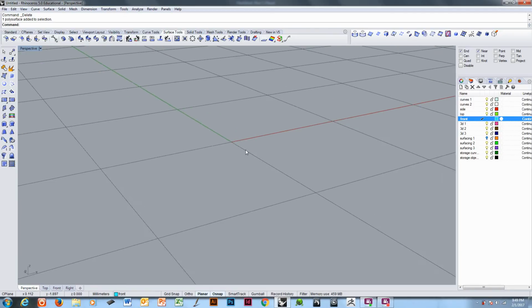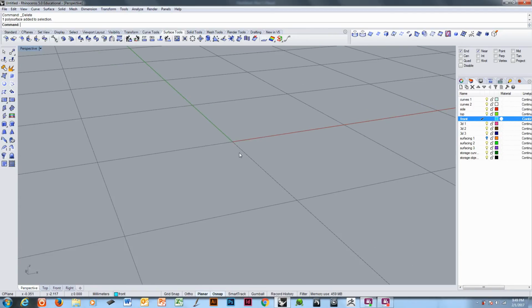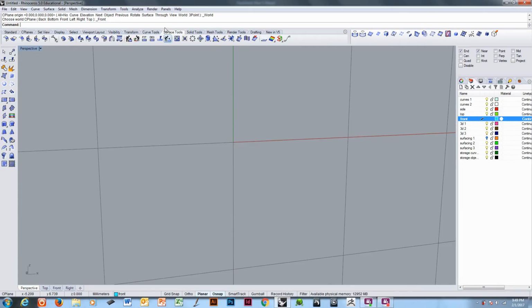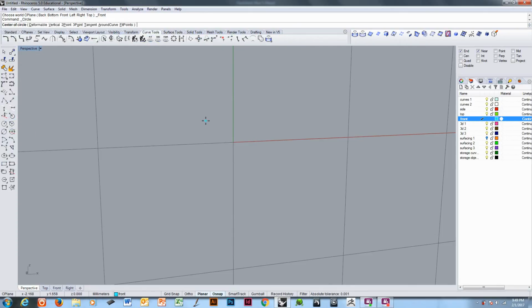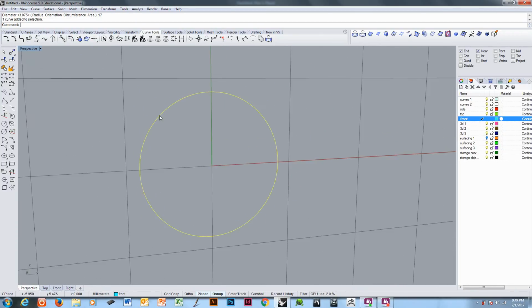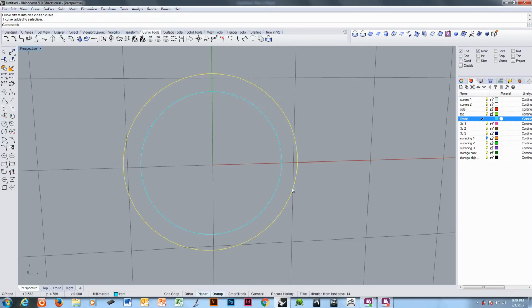Beginning preparation, I'm going to draw the front view of the ring shank. The ring shank is going to be a standard 17 millimeter diameter bore. So circle center radius, origin at 0, diameter 17. I'm going to offset this ring bore 2 millimeters. That's a good standard ring shank thickness. In order to get a nice swell on the shank, so it starts thinner under the finger and expands up over the shoulder, I'm going to move this outer profile curve up 0.3 millimeters.